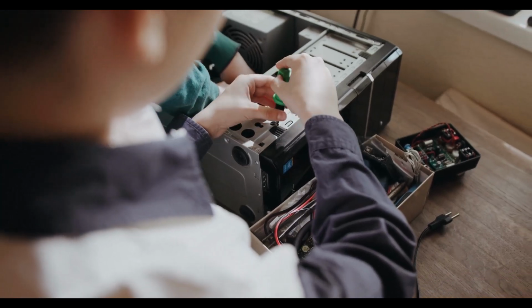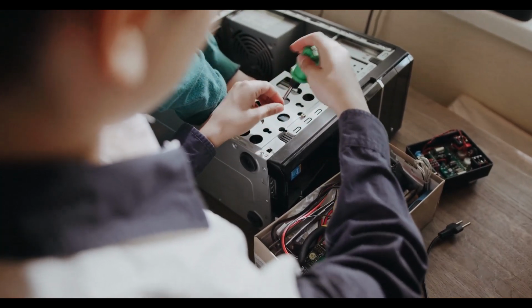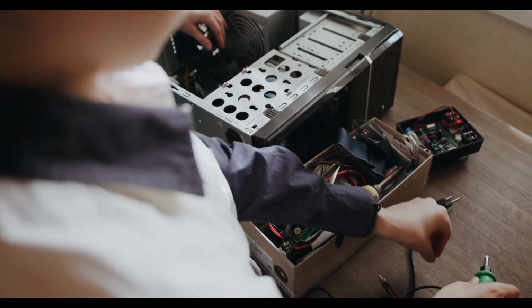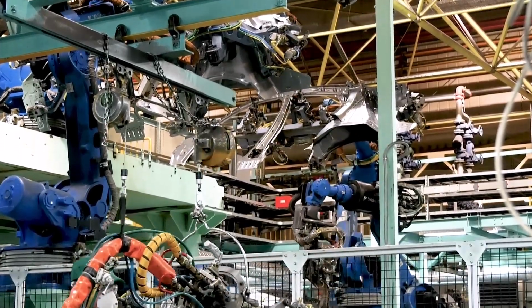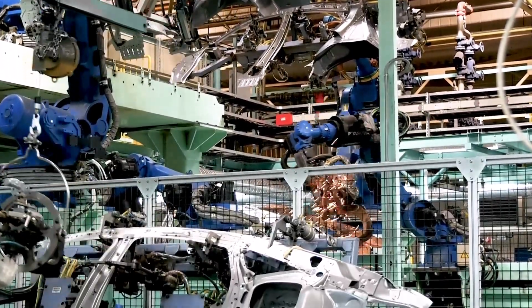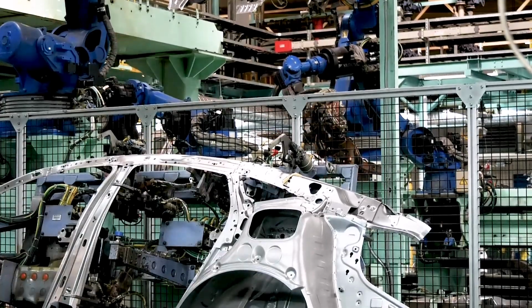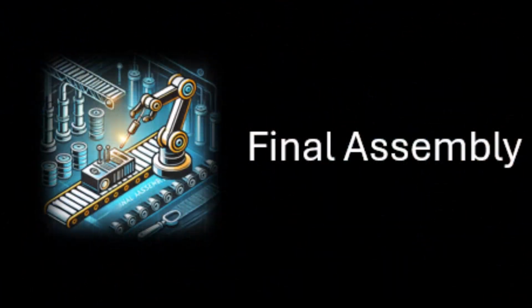Usually there are a couple of loops. So you test stuff, you realize something doesn't work, you redesign it. So you'll have to change your schematic. It could be a simple change of a resistor value or capacitor value, same layout, just changing part values, or maybe a different op amp or a buffer with the same footprint, or it could be a whole new PCB.